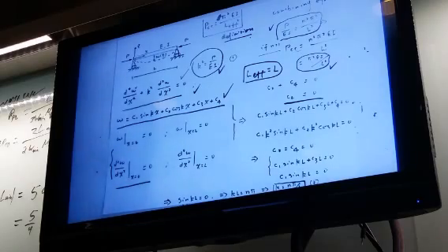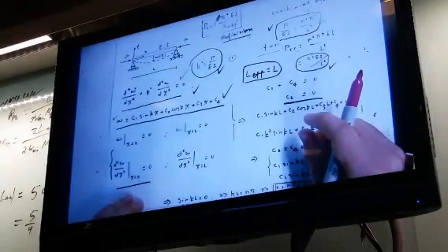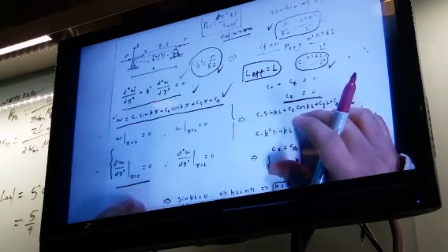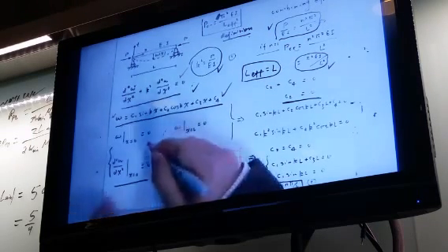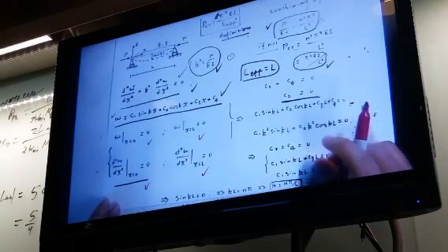And then we assume some form for the deflection. And this displacement along the vertical direction will contain four constants, C1 until C4. Those constants will be determined by the boundary condition. And when you are using boundary conditions, you can form four equations, four unknowns, right? C1 until C4. This is the first boundary condition, second one, third one, fourth one, for this beam structure.